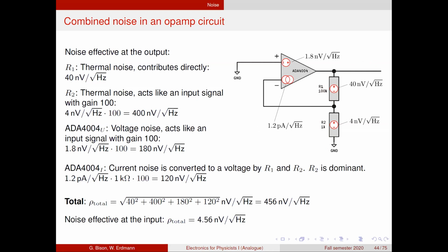And it means it's power that our amplifier dissipates all the time. So if you want to build a really low power amplifier, for your smartphone, you wouldn't want something that drains your battery all the time. Then it's a disadvantage to go to really small resistor values.